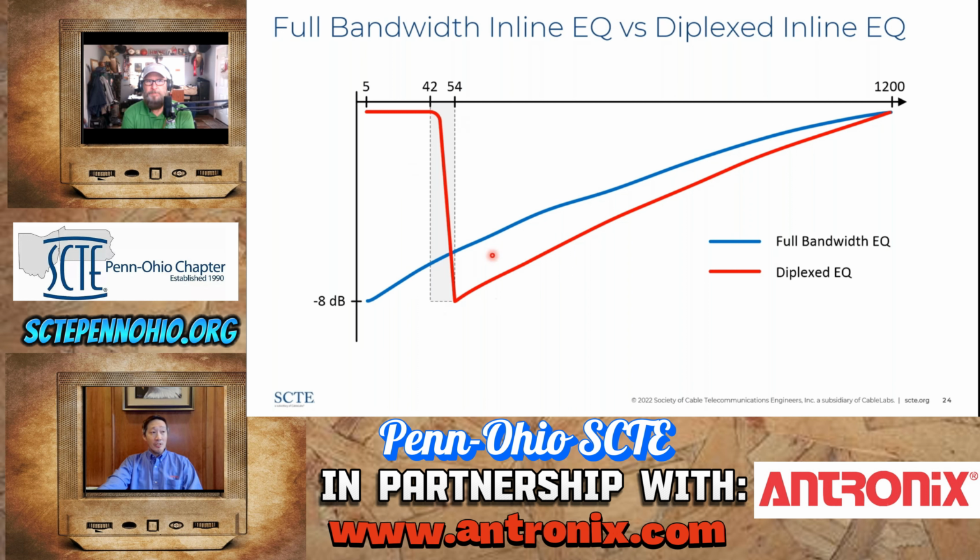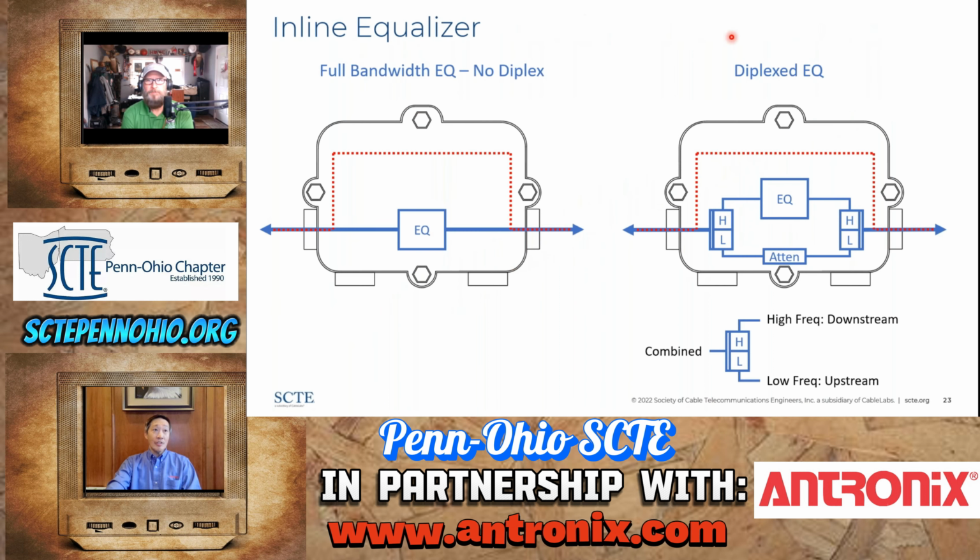But since there is a diplex filter in here, as networks migrate from subsplit to mid-split to high-split to ultra-high split or whatever, or no diplex, using a full bandwidth equalizer allows us to make those network split transformations without coming back to revisit these inline EQs. So if you do have a diplex version in there, as you change the architecture in your network, you may have to find all the diplex versions of the inline EQs you have in the network and replace them.